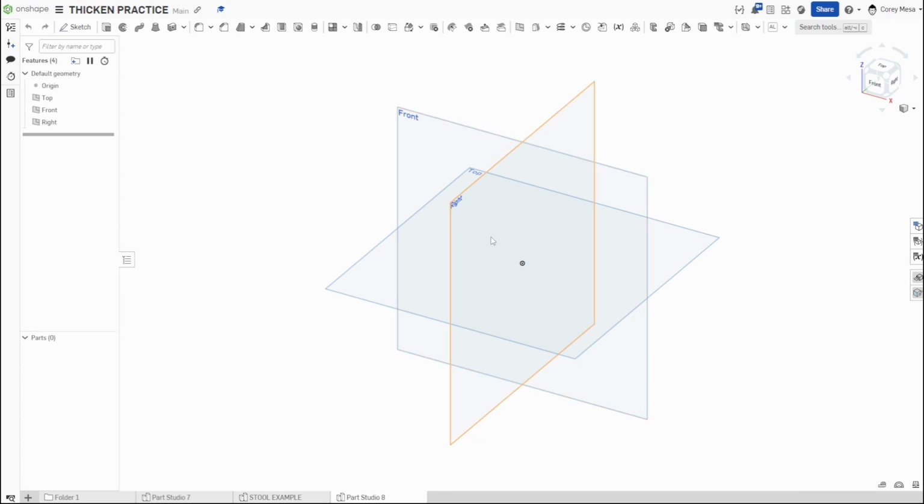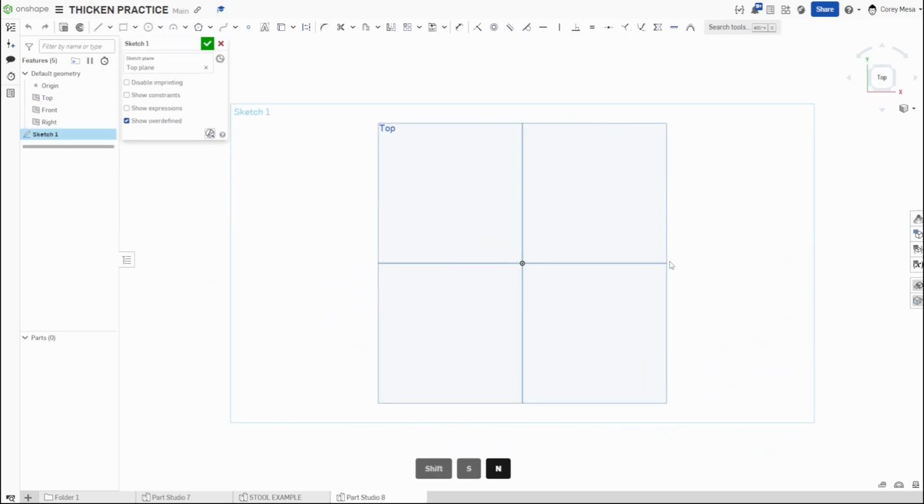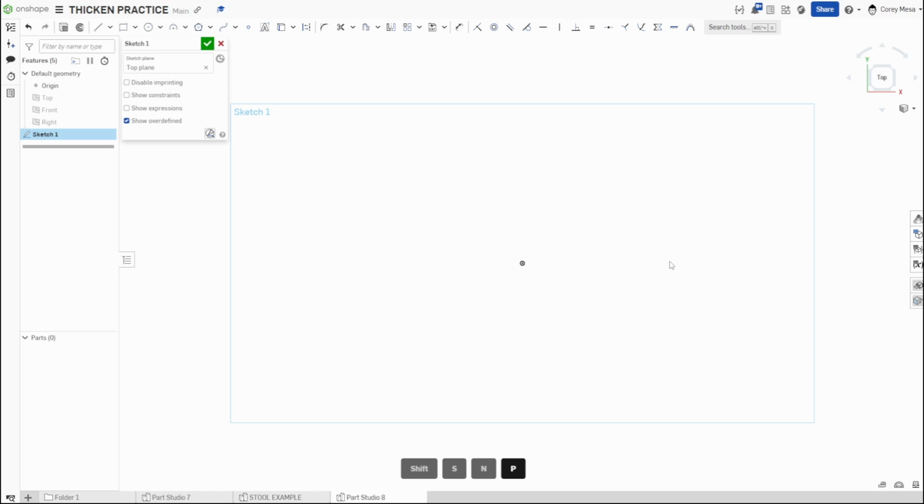But basically, when anything's defined, let's get a sketch started. What it needs to know is its relation to the origin. So if it's just floating off in space, it doesn't know what it's doing because it doesn't know where the origin is. So what he's talking about is when I draw my circles, I try to tell all my students to always base everything off the origin because it knows where the origin is and it's going to define everything. So if everything's based from there, it knows where it's at.